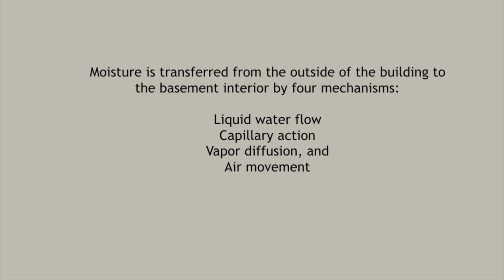a spring runoff. 2. Interior moisture sources such as humidifiers, unvented clothes dryers, bathrooms, and cooking, as well as the moisture in concrete after construction. And 3. Exterior humid air that enters the basement through penetrations and condenses on the cooler surfaces.